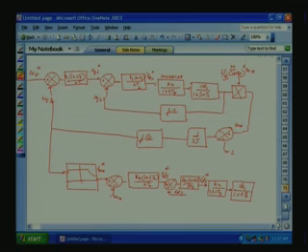Okay. This one, stator, that is mutual plus leakage, because this is the flux producing component. So the mutual inductance time constant comes into the picture. So this will come here, and again if you are using a filter we can feed it here. This is our current reference. Now, IDS times 1 by (1 plus STR) is our IMR. So this loop also we can design if you know the input output relation, same like what we use for the separately excited DC machine or front end AC DC converter.